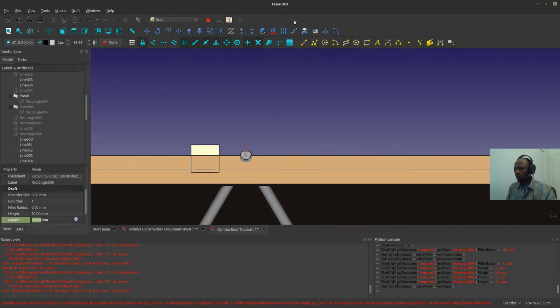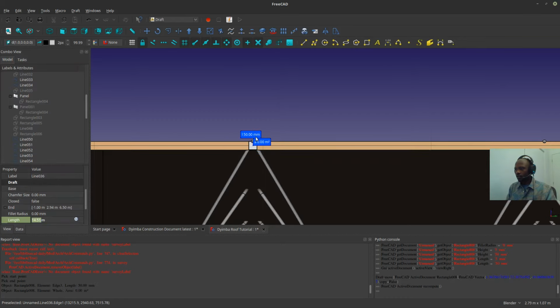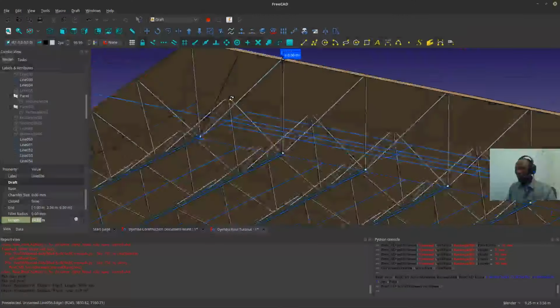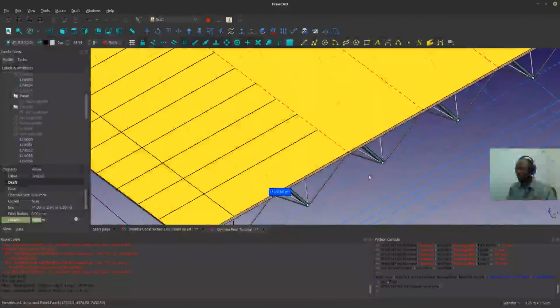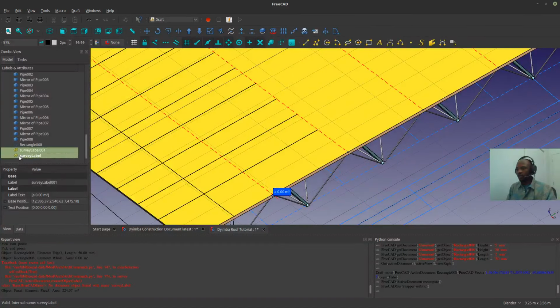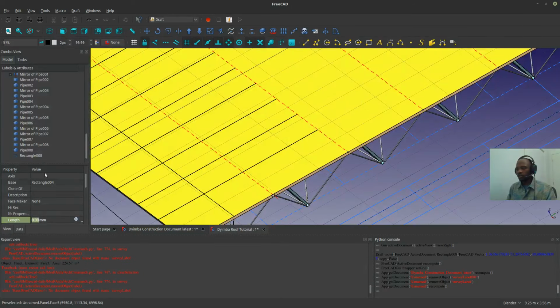Now I'm going to select this. I do not want to copy, but I certainly want to snap you here at the center. And let me check the direction of my plane. Now I want to be on this face with my plane. And I want to make this wireframe because I want to see through.